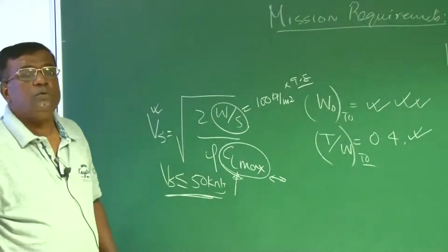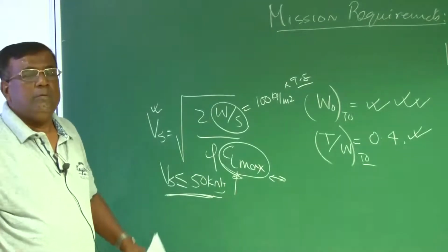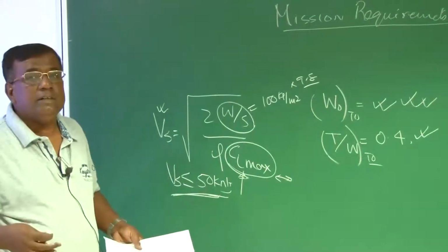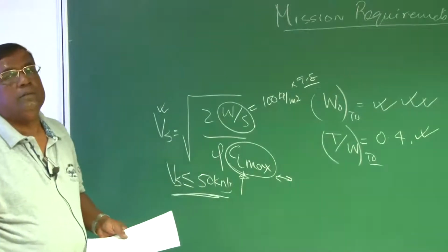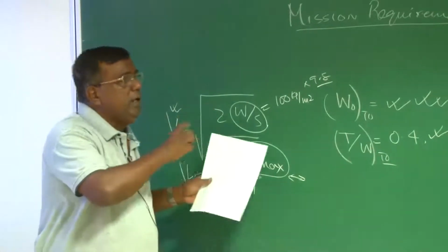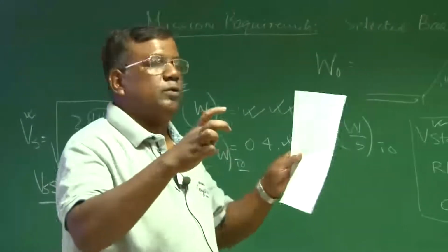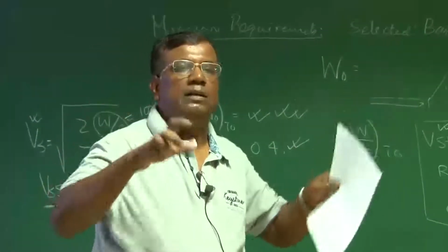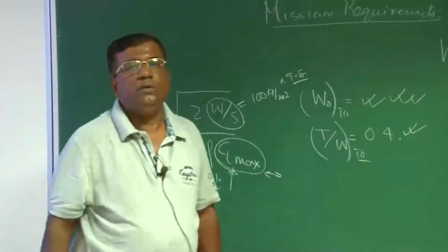That means I have to look for an aerofoil whose CL max is higher, and I have to look for other high lift devices which can enhance the CL max locally during takeoff and then retract afterwards. So all these combinations we'll be trying, right? And that is how you compromise every factor and find out, okay, this is optimal for me or adequate for me.